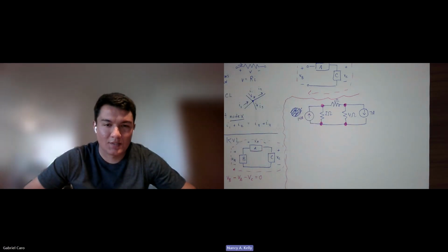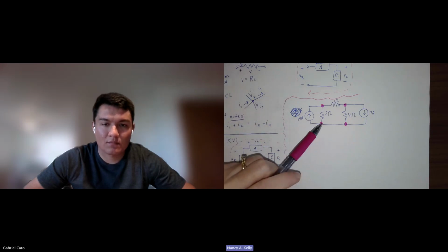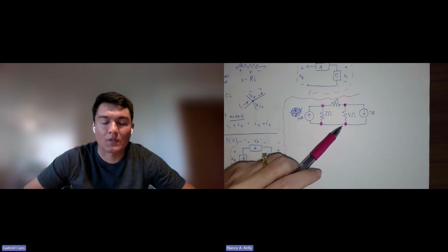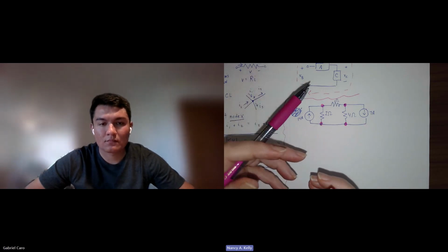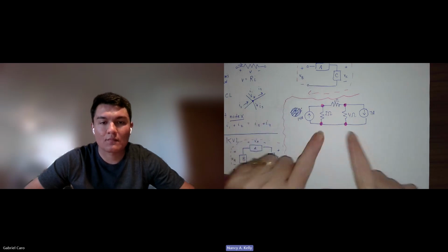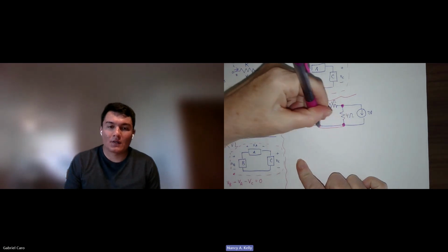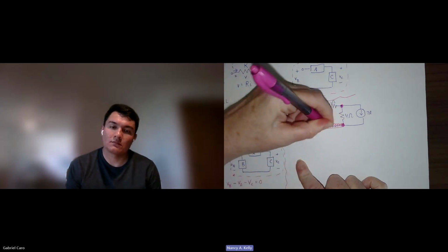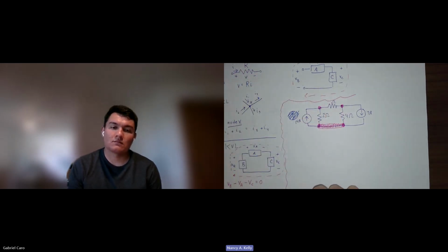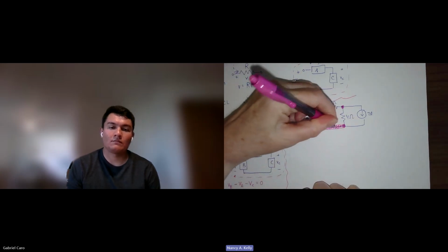Yes. Okay. So a node is where we have the wires joined together, but electrically, these 2 points are identical because you see this is just a wire. Since the wire is perfect, you could make it super short. If you shrank it down, think about what would happen. You shrink it down to nothing. It'd be one. You can't do that at the top because there's a resistor there, right? Those are electrically different. We assume there's a change in voltage here. Since there's no change in voltage along here, we can consider that to be a single node. Okay, so yes, there are 3 nodes in this circuit.